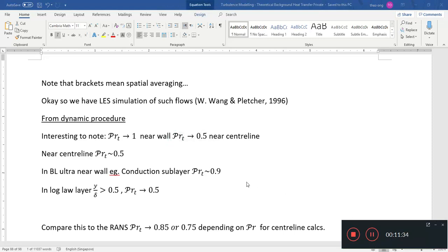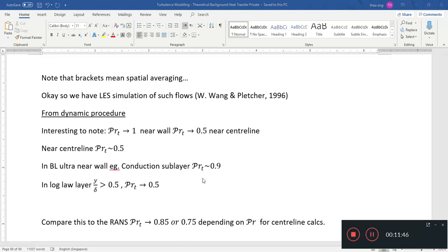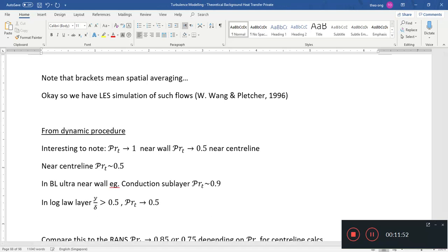Yeah, this one was from Wang and Fletcher. I'm not sure if it is supersonic or what, but okay, I just double checked. These values were for low Mach numbers, Mach 0.01. This is effectively incompressible, because a Mach number of less than 0.3, and this is about 30 times less than 0.3, you can roughly think of as incompressible flow. So it's easy in that sense.